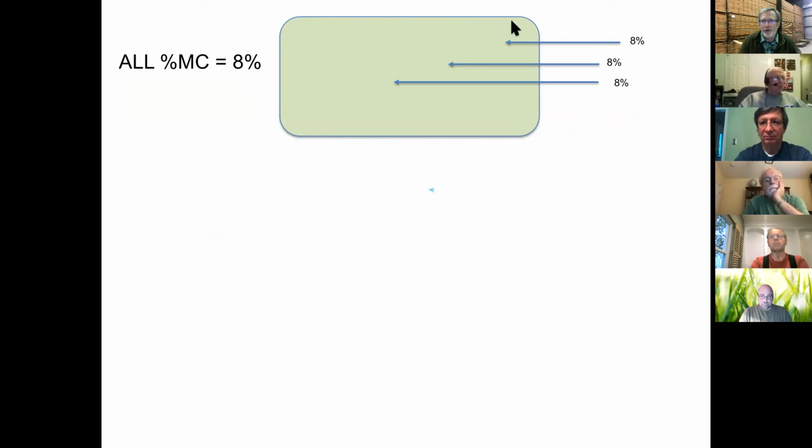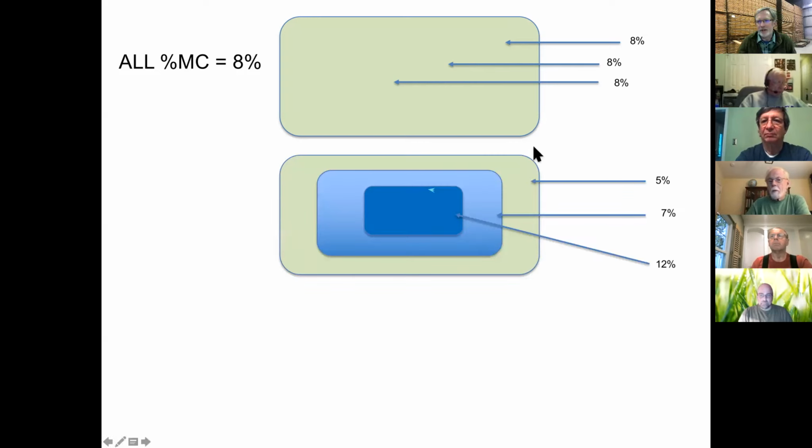Well, ideally, what we think of is that the outside of that piece is at 8%, the middle, halfway into that piece is about 8%, and the dead center is probably at 8%, right? That would be an average of 8%. That's basically what we want. We want uniformity so we don't have any moisture changes or dimensional changes while we're working with wood. But hey, guess what? This cross section is also an average of 8%. How could this possibly happen?